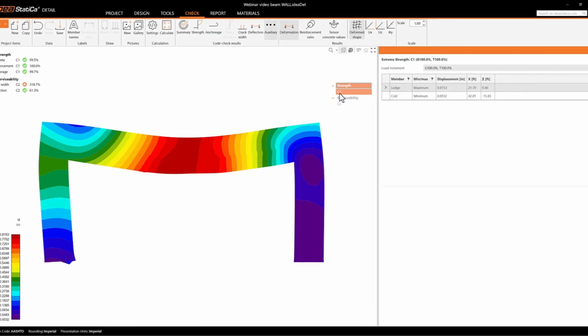So now you can look at the deformation of combination number 1, which is a strength combination. The deflection is one result, and the deflection limits are based on service combinations. But if we're running FEA, we can have the deformation of both combinations. This is very helpful to see if the structure is deforming as you expect. So this is kind of a sanity check.